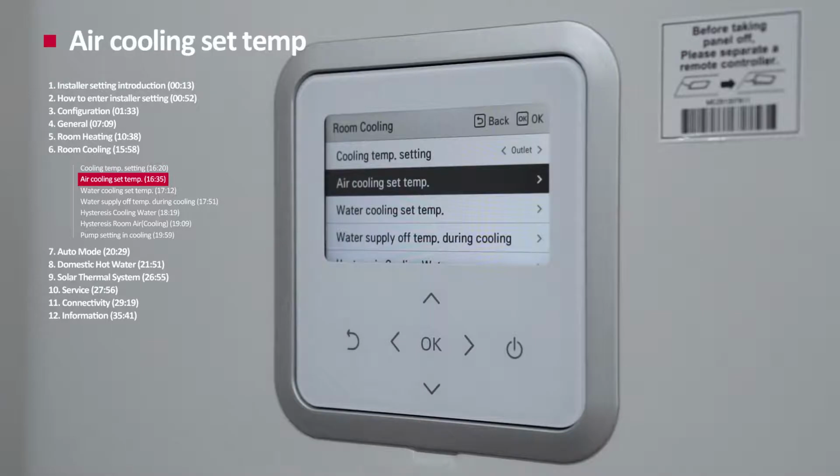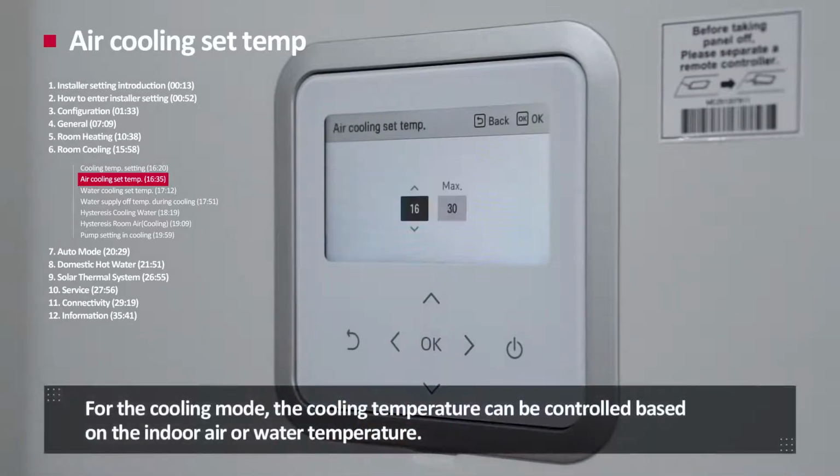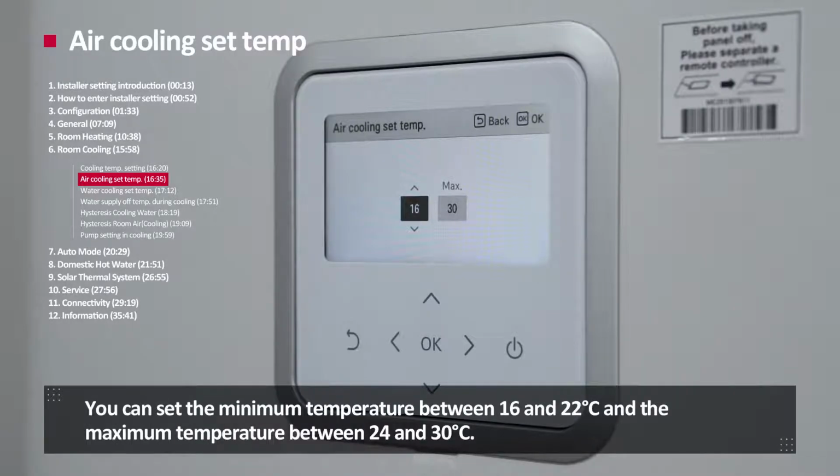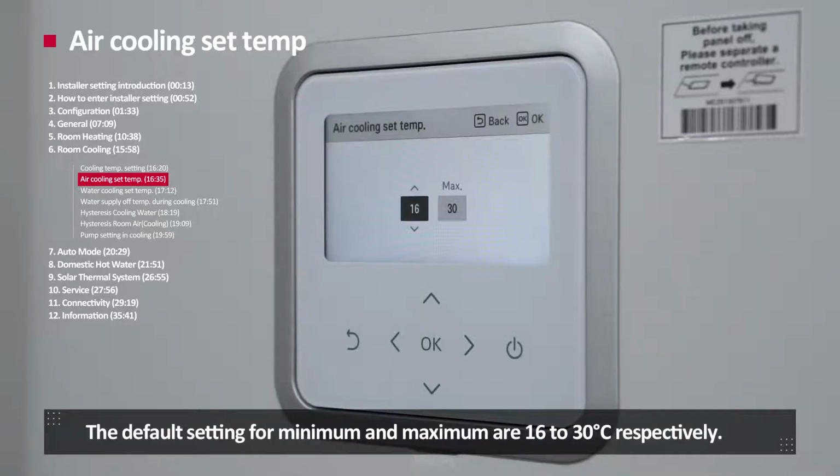Air cooling set temperature. For the cooling mode, the cooling temperature can be controlled based on the indoor air or water temperature. If your cooling mode is controlled by indoor air temperature, you can determine maximum and minimum temperature by using air cooling set temperature function. You can set the minimum temperature between 16 and 22 degrees Celsius, and the maximum temperature between 24 and 30 degrees Celsius. The default setting for minimum and maximum are 16 to 30 degrees Celsius respectively.